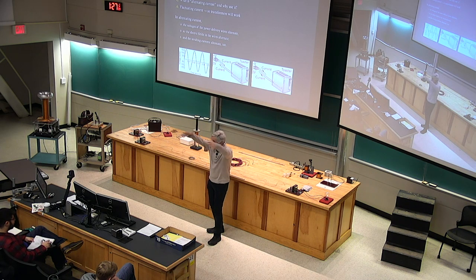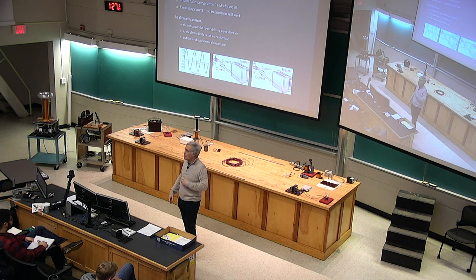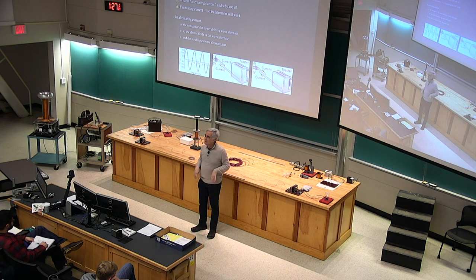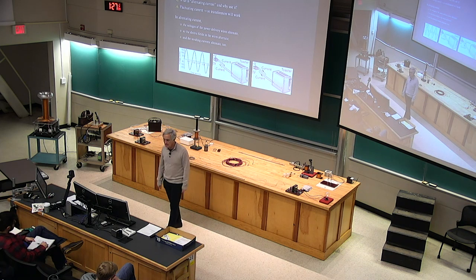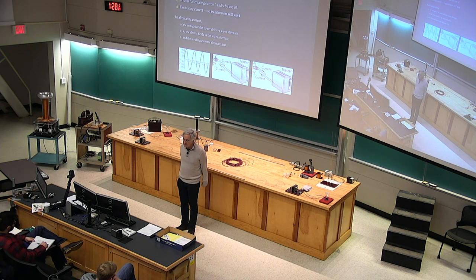If you connect the frame to ground, and any wires get loose inside the washing machine and touch the frame, they will exchange charge with the earth and not with you. It typically will blow circuits and blow circuit breakers for safety reasons, but it has been for a long time a useful safety feature.